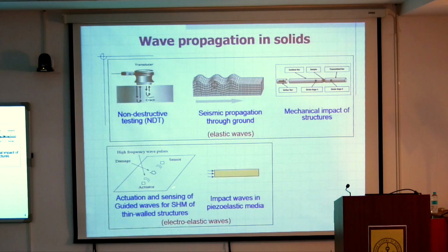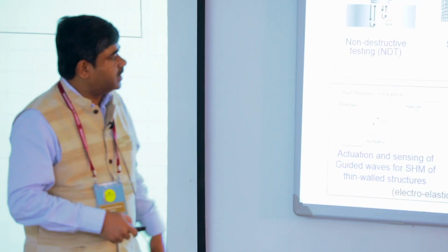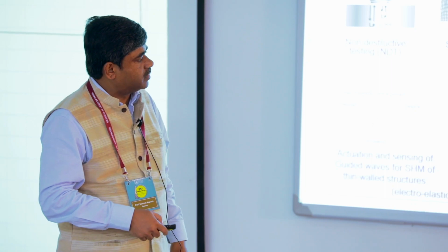This is another example. You have a structure, a simple cartoon: a plate with a piezoelectric actuator and a piezoelectric sensor. When you actuate the piezoelectric actuator through some electric signal, you can excite an ultrasonic wave.